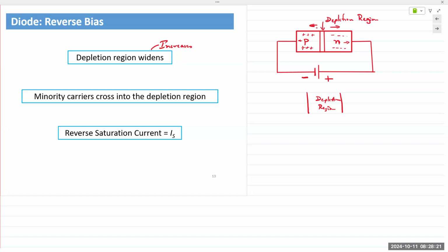That is also actually something that a multimeter would do. You want to test a diode, you plug it into a multimeter. The multimeter applies a small amount of current and voltage. If the diode turns on in one direction, it'll tell you, okay, this might be forward bias. The diode should be off in the other direction. If it's on in both directions, or off in both directions, then something's wrong. That's where you just want to know whether it's on or off. Make sense? Yeah.